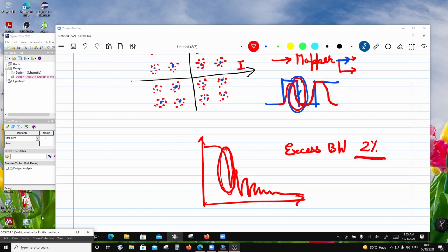So I have this window, I can approximate this window as a rectangular. I can represent this as a Hann window. I can represent this as a Hamming window. I can represent this as a flat top window. So various windowing is possible here. And the other thing is I can do frequency equalization.